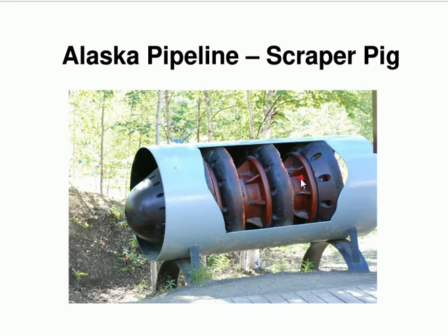It would be a nightmare as well if that thing gets stuck anywhere in the pipeline. You would have to literally cut it open, get it out. But it's just pushed through with the liquid behind, and over here it looks a bit like a bullet, doesn't it? Like a massive bullet. And then here at the front you've got the thing where it goes through. And then on the side, these are the scrubbers. So these scrubbers, they try to clean any deposits from the wall and pick them up somehow. But yeah, it's just the pressure of the medium, the liquid or gas inside the pipeline.